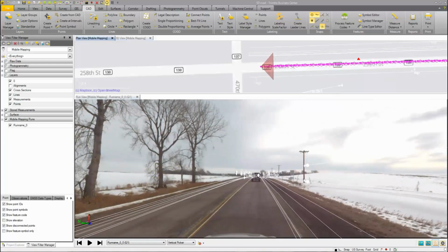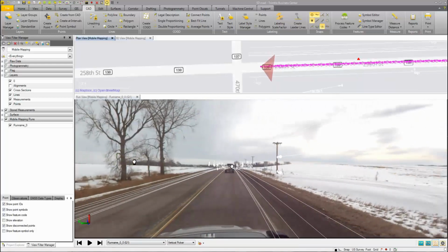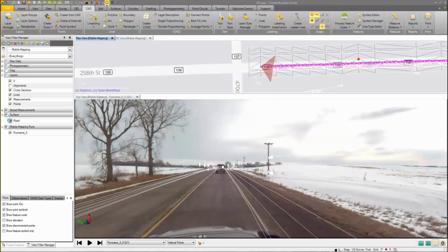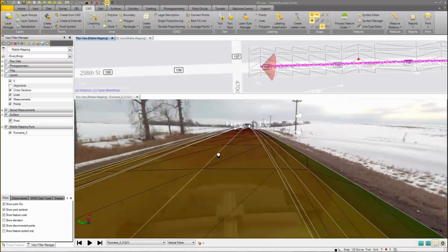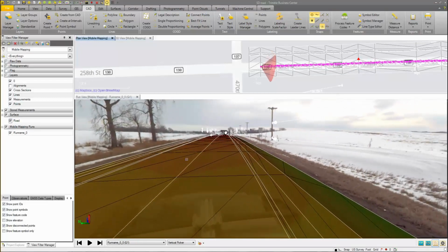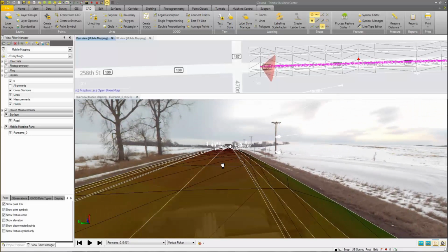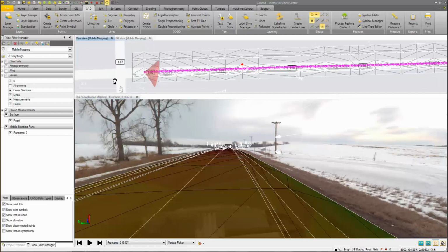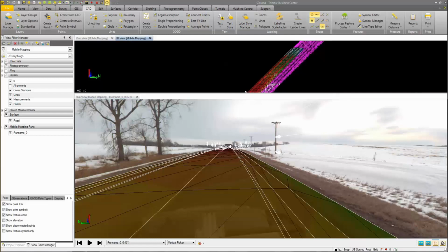So one example that I have here is a surface file for this road, just a proposed road surface. Go ahead and turn that on, and you will be able to see that here in 3D overlaid on our image with our break lines and other road surface geometries. And we can get that up in the top in our plan view and traditional 3D mapping view as well.